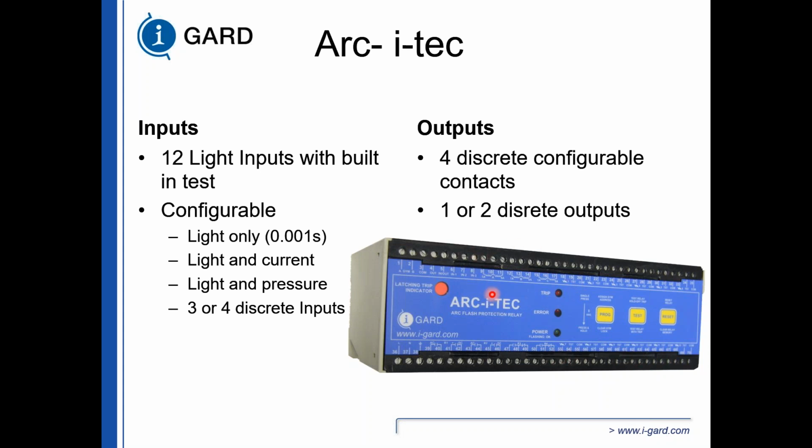You can interlock it with current with the CT, and we have a 5 amp and a 1 amp input. These are the inputs and outputs, and the output relays here. So 3 normally open, 4 normally open, and 2 changeover.